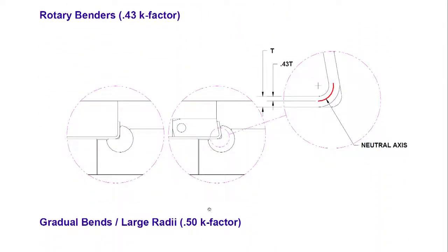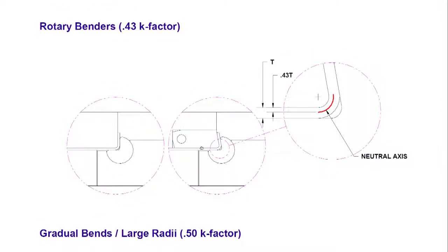In here they have shown a movable rotary bender. What does this rotary bender do? This inside part also moves and then gives you the natural bend. Have you seen here? Instead of that being a rigid thing where it is forced to slide, this part of it moves and bends with it. You see this vertical part here, no? You see here, then you see how it bends over here.